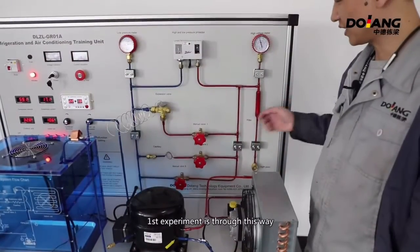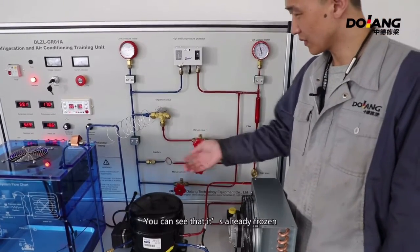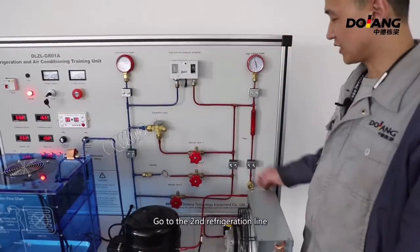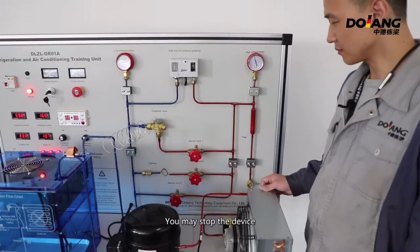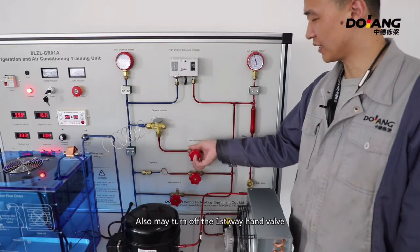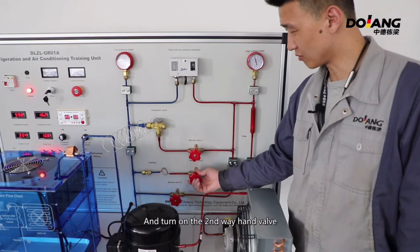The first experiment is through this way. You can see that it's already frozen. Go to the second refrigeration line. You may stop the device. Also turn off the first way hand valve, and turn on the second way hand valve. Make sure the other 2 ways are closed.